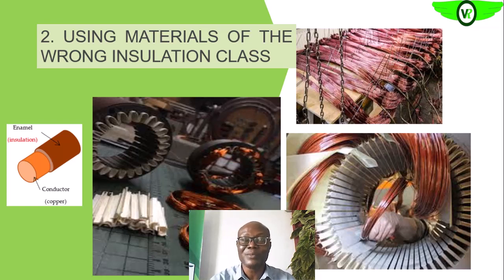If you use a material of a wrong temperature class, especially a lower temperature class, you will see that the insulation will be destroyed during normal operations of that asset, the electric motor, generator, or the transformer.